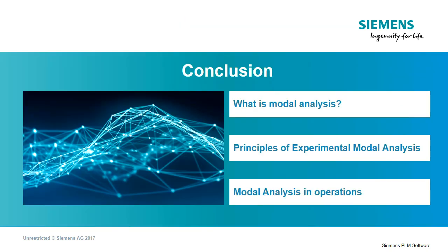In this seminar, we've explained the fundamental concept behind modal analysis. We have seen some practical examples and how modal analysis is used throughout the industrial product development process. After introducing the concept of natural frequencies, modal damping, mode shapes, frequency response functions, and how those are heavily interconnected, we discussed the main steps in experimental modal testing and analysis, from instrumentation to validation of the modal model.